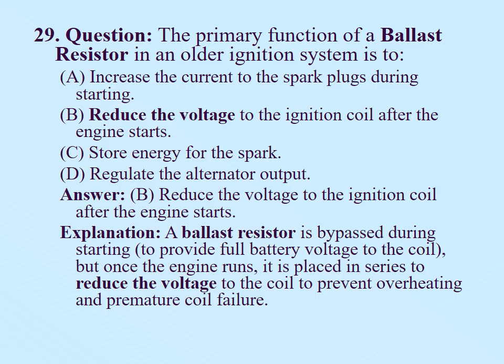That is, a ballast resistor is bypassed during starting to provide full battery voltage to the coil, but once the engine runs, it is placed in series to reduce the voltage to the coil to prevent overheating and premature coil failure.